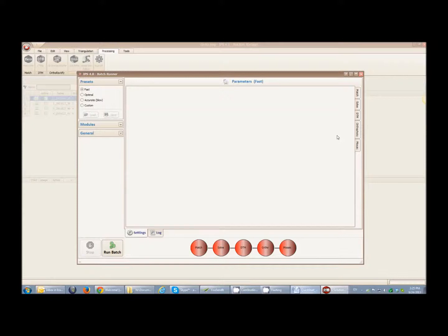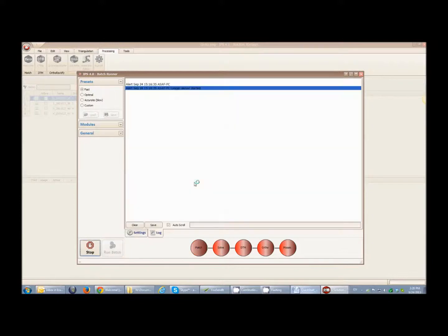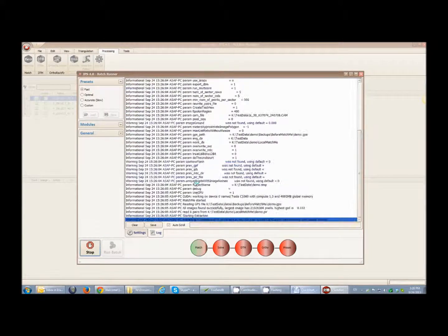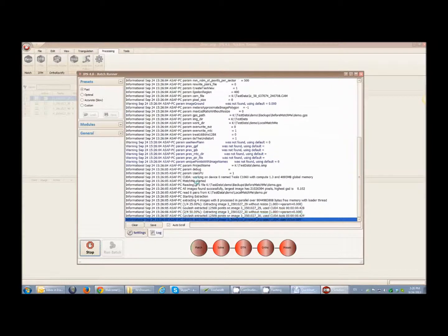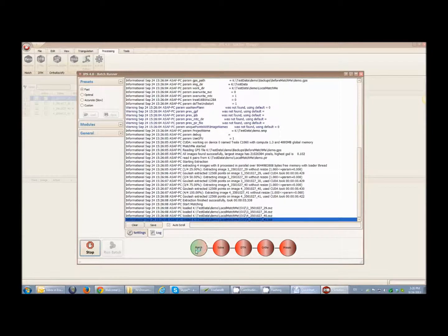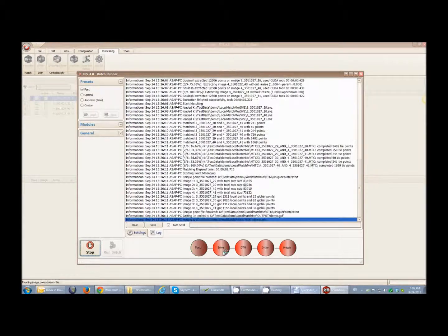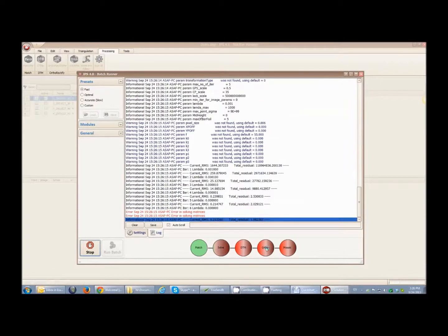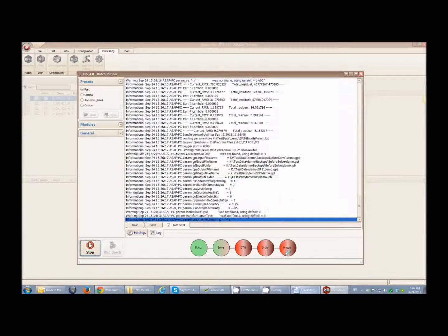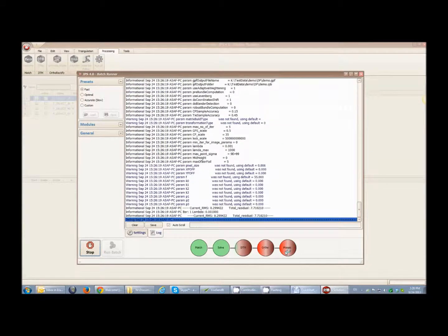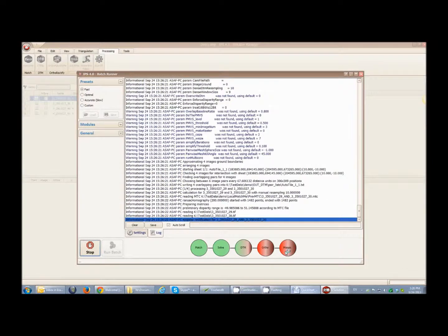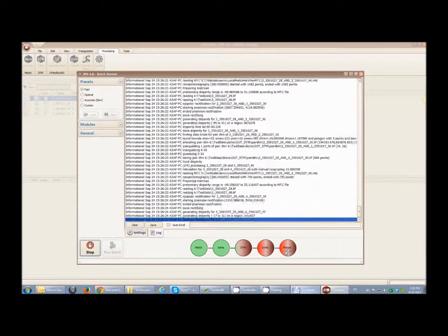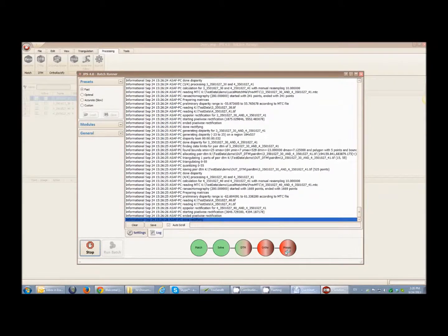Press the Run Batch button and Solution Manager will automatically go through all the necessary actions to create the output. The application will run through the following modules: Match, Interest Point Creation and Matching, Solve, a statistical bundle adjustment process, DTM creation, Ortho Images creation, and Ortho Mosaic creation. Each module turns green once the process is finished, so you can easily determine which stages have already been performed.